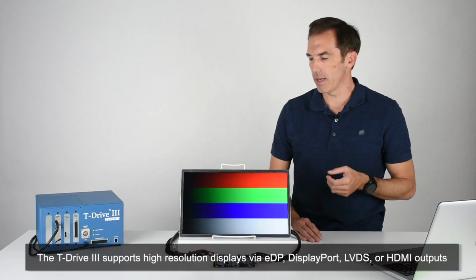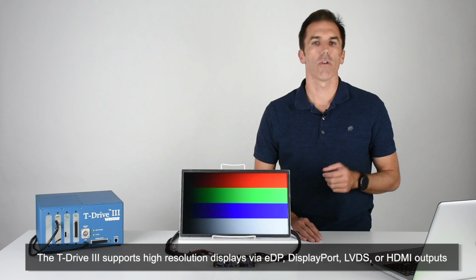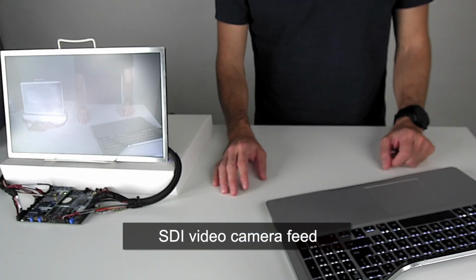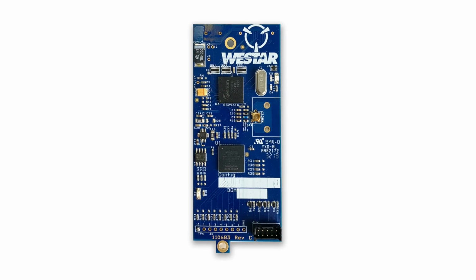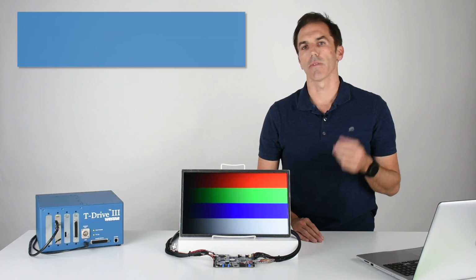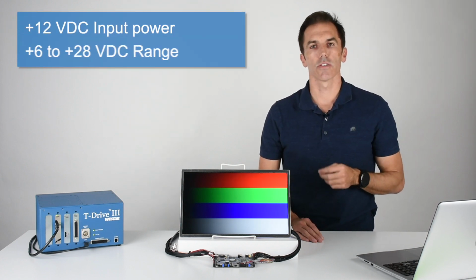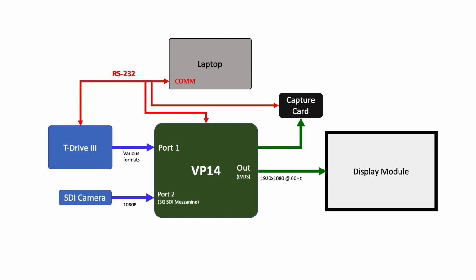For example, 1080p, 720p, and a few other formats. For our second video source, we have a 1080p SDI video camera, which is over here, connected to port 2 using an SDI mezzanine board. Our VP14 is typically powered with a 12-volt DC supply, as we have here, but it can accept anywhere between 6 and 28 volts DC. For configuration and dynamic control, we are using RS232.